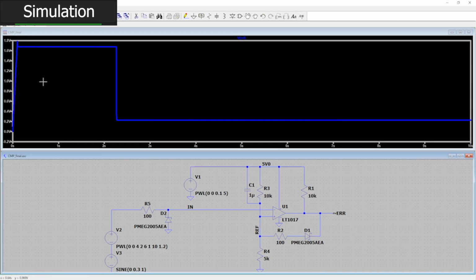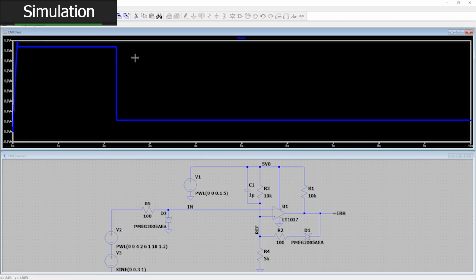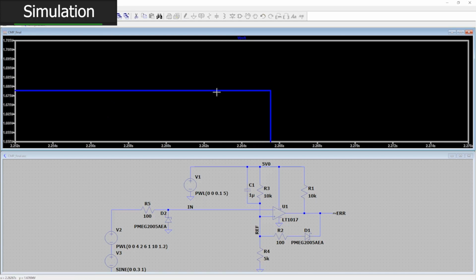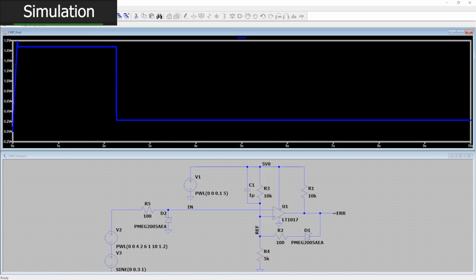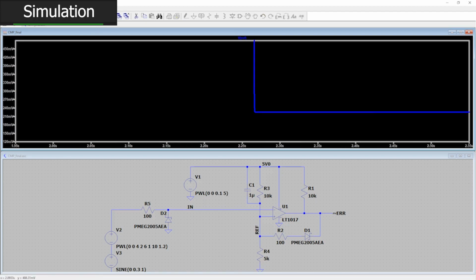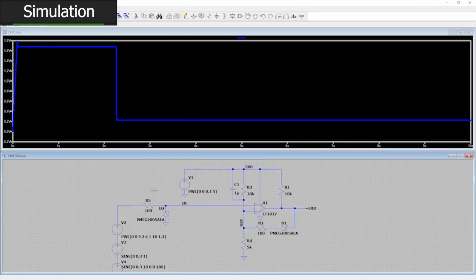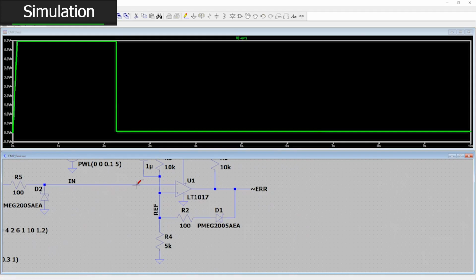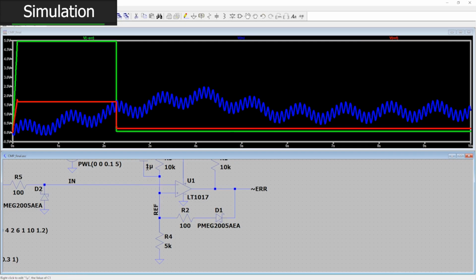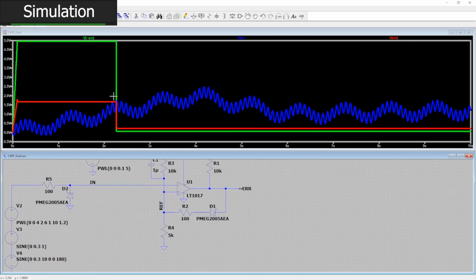Rerunning the simulation. And hey, look at that. There's that little transient. And okay, I might have made it look a lot more dramatic than it really is, but there's a little bit more rounding on those corners. Excellent. But overall, the steady state threshold wasn't changed, and the overall circuit function is working. That's pretty cool. We have a latching comparator circuit.